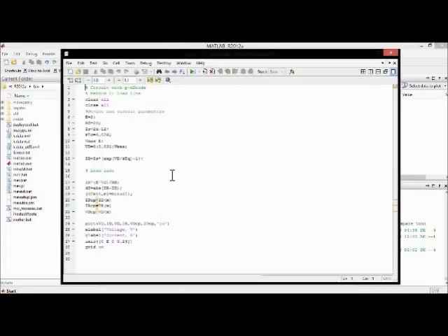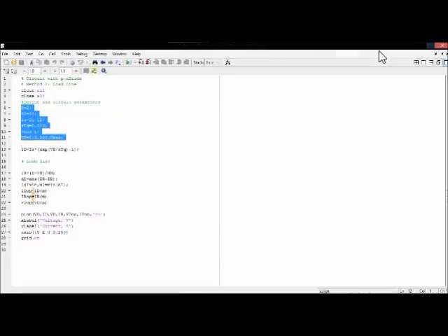So this is the program which I have written. This is quite simple. You need to write clear all, close all. The EMF value E is given as E equals 2. RB, that is the resistance value, is given equal to 20. And IS, that is the saturation current, is given as 2e-12. This is the format of writing exponentials in MATLAB.